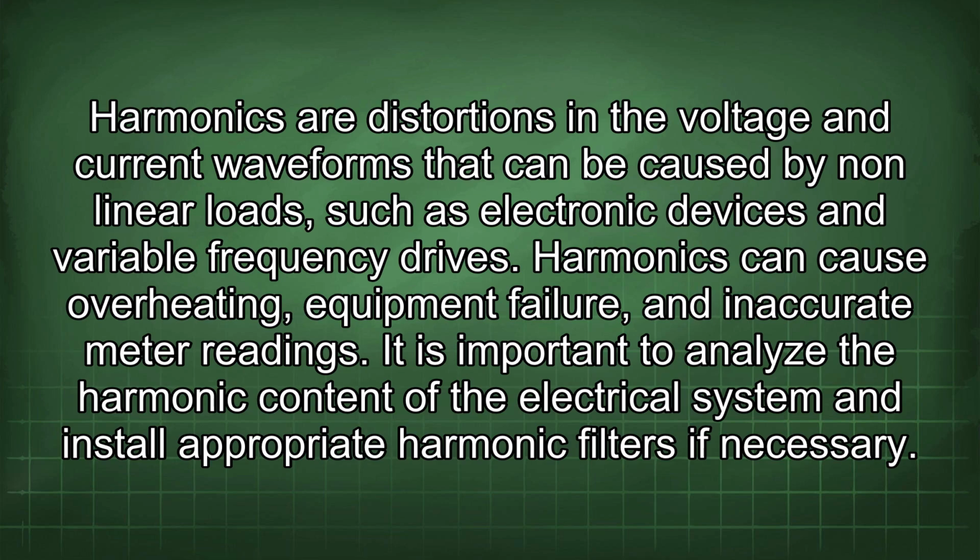Harmonics are distortions in the voltage and current waveforms that can be caused by nonlinear loads such as electronic devices and variable frequency drives. Harmonics can cause overheating, equipment failure, and inaccurate meter readings. It is important to analyze the harmonic content of the electrical system and install appropriate harmonic filters if necessary.